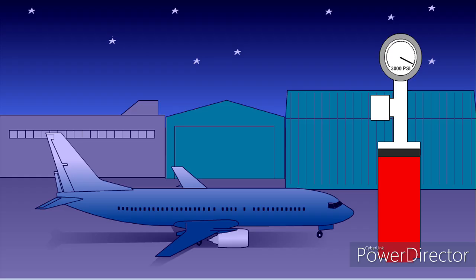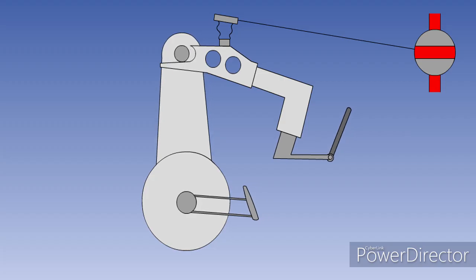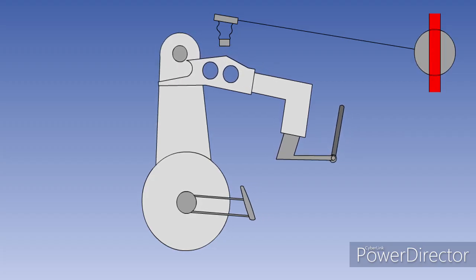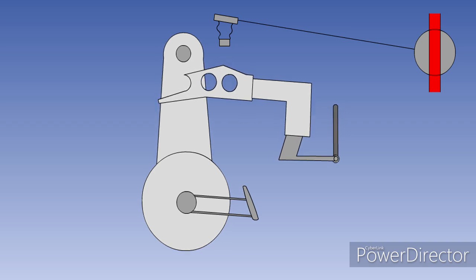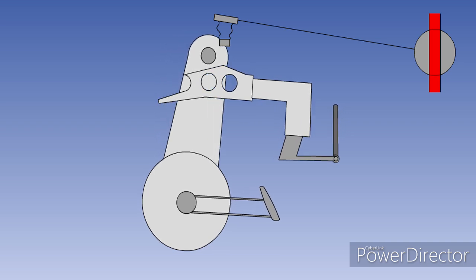A fully charged brake accumulator will have sufficient fluid to hold the brakes fully on overnight. To release the parking brake, the pedals are depressed, allowing the lock pin to release from the pawl and the lever to spring forward.